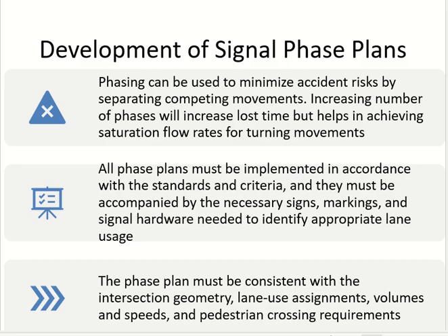For example, if you have a separate phase for left turning, then you also need to separate the lanes. That means you also need a separate lane for left turning. You cannot have a combined lane for straight and left and keep a separate phase for left turning. It's not possible. The lane has straight and left, and the signal is only showing left, so that lane cannot be used.